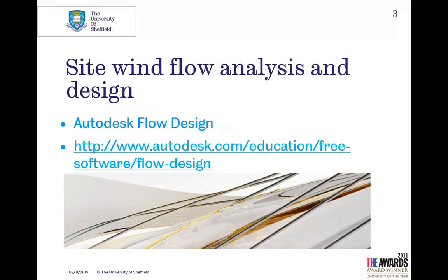So I demonstrate the software for performing urban wind flow. So looking at a site and looking at the external wind flow on that site. And for that purpose, it's okay. It's quite reasonable. You should not confuse this with interior ventilation simulation. If you look at this software, you will find people online demonstrating it for internal wind flow and ventilation flow, but it's not really good enough for that. So I'm not suggesting you use it for internal simulation.